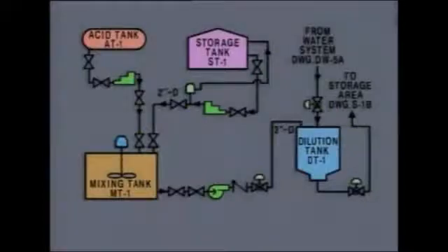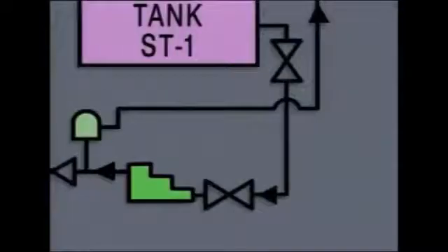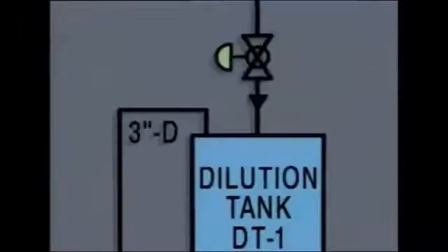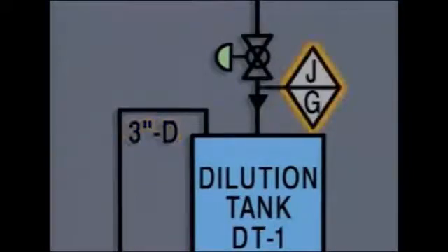The symbols for the valves and other equipment on a process flow diagram are connected by lines that represent the flows of materials in the system. Lines that cross with a hump or a break in one line represent material flows that are not connected. Lines that cross like this, without a hump or a break in one of the lines, represent flows that are connected. The same material flows in all 4 legs of the piping. Some diagrams include codes which indicate piping diameter or the piping material specifications. The codes are helpful in locating and identifying specific pipes in a system.